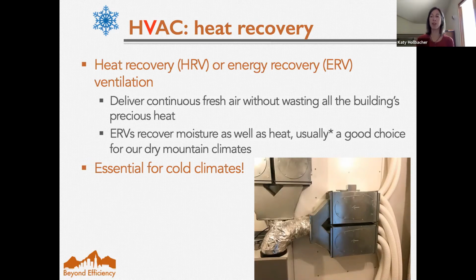If you're designing a multifamily building that's catered to families, and you've got an 800 square foot apartment with 4 people living in it, there's a lot of added humidity just from, again, people breathing and potentially a lot of cooking. So it might be bad to have an ERV in that space. Again, always just be aware of what the situation is.